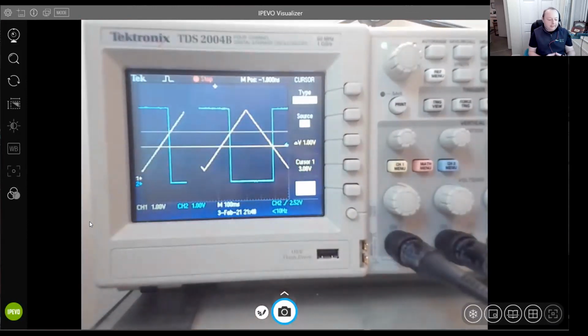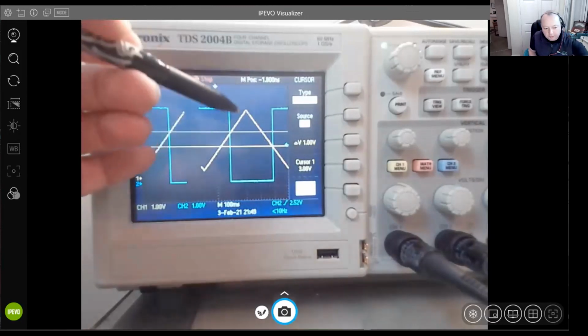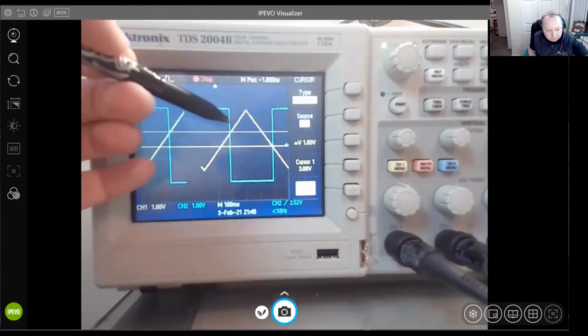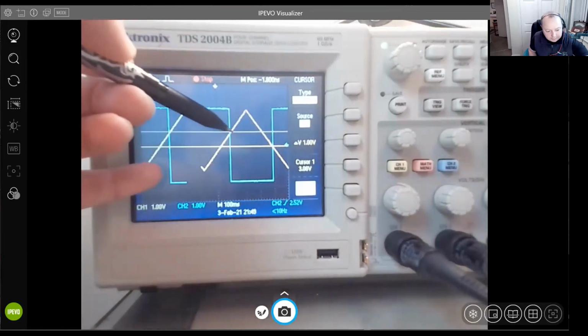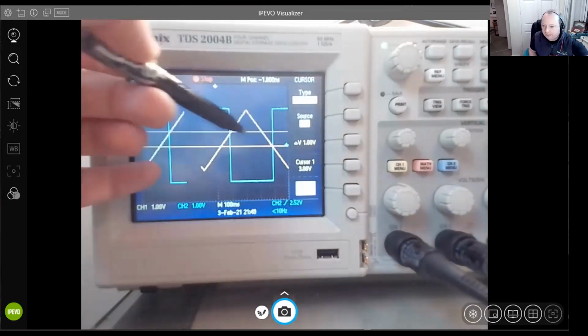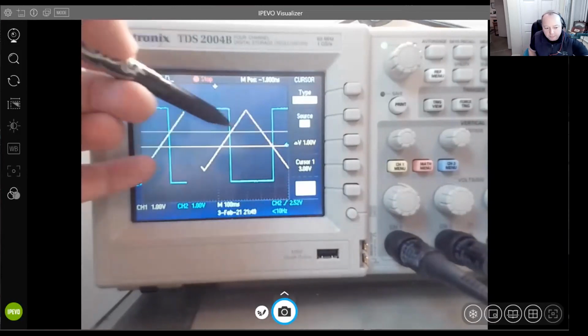If I'm using an analog circuit, say a variable resistor, or maybe an audio input, I'd probably think about using a Schmitt trigger, because there's no danger of ever having messed up logic levels.